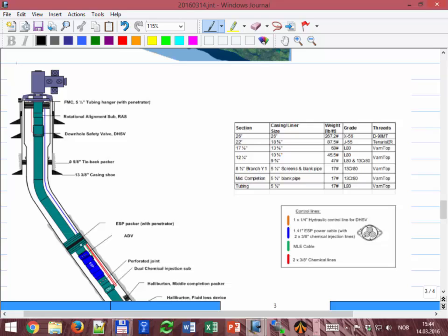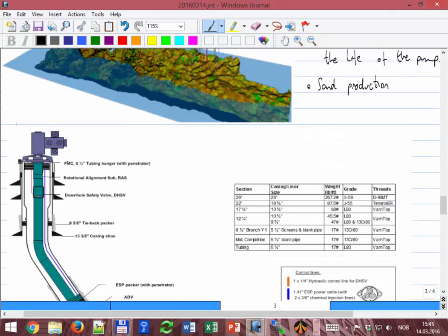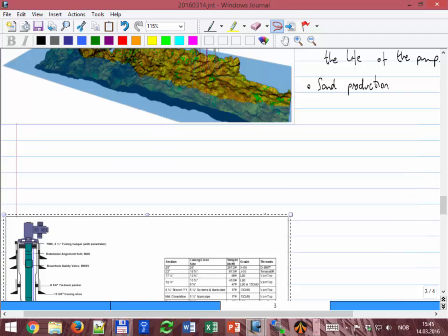And then the cable passes through the packer, that is blocking the annular space, that is the barrier of the annular space. And then from here it splits into one power cable to the ESP, and then it goes further down to the suction of the liquid from the formation to inject this de-emulsifier agent. Okay. There are some other components there that, you know, let's not dwell too much on them.